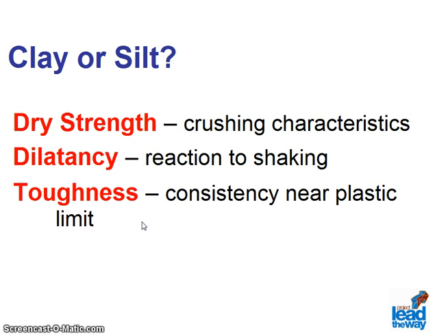These tests are the dry strength test, which determines the soil particles' crushing characteristics, the dilatancy test, which determines the soil's reaction to shaking, and the toughness test, which determines what kind of consistency exists near the plastic limit.